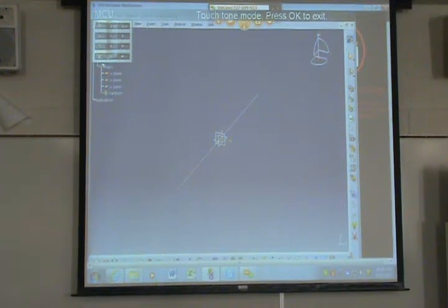Okay. In top down, we are creating the master assembly first. This is where the skeleton will exist. Okay? Once we create all this stuff, we're going to start adding sub-assemblies. And you can even add parts if you want to inside of the master. There's nothing that says you can't.